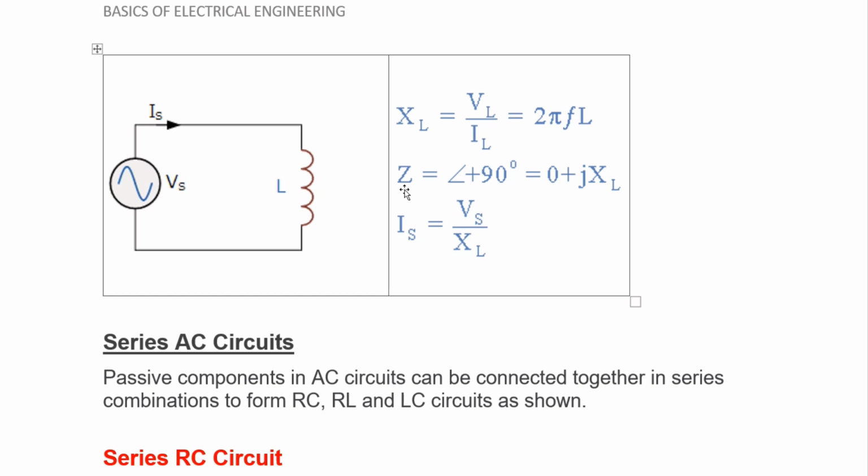So Z is equal to plus 90 degree. That means voltage leads here. The voltage leads here, not current leads here. Okay. So current lags by 90 degrees with respect to the voltage, and this is shown as zero because here also resistive component is zero for the purely inductive circuit. Pure inductor does not carry any resistance. It is supposed not to carry, but it is an imaginary situation.